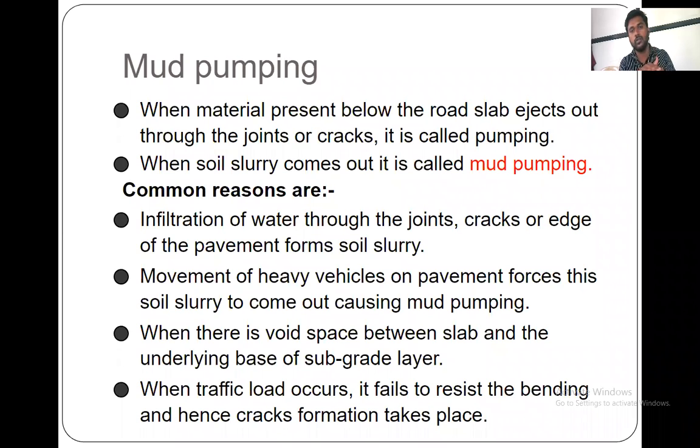Due to the application of that heavy load, the mud or slurry tries to come out. That is called mud pumping. It also occurs when there is a wide space between the slab and the underlying base and subbase layer. If there is a wide gap provided, then the mud pumping will be there.